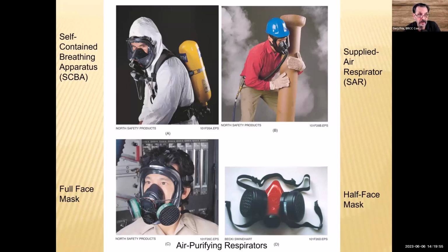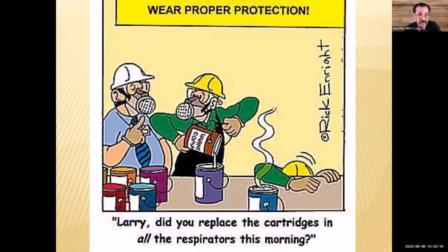So you have to get them snug enough to be sealed, but not any snugger, because there are muscles across the top of your head that will ache like crazy, and it tends to turn into a massive headache. Okay, so then the cartridges on the air purifying respirators have to be cleaned. They need to be replaced.